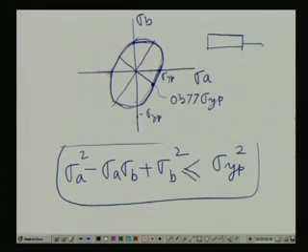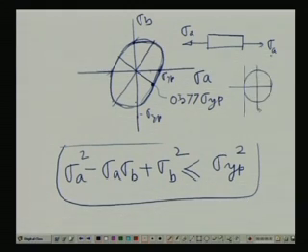If we have a simple tension test, then this comes out to be sigma A only, and if we go up to the yield point, and in this case we plot a Mohr circle, then we get a value sigma A like that, and this is tau max.